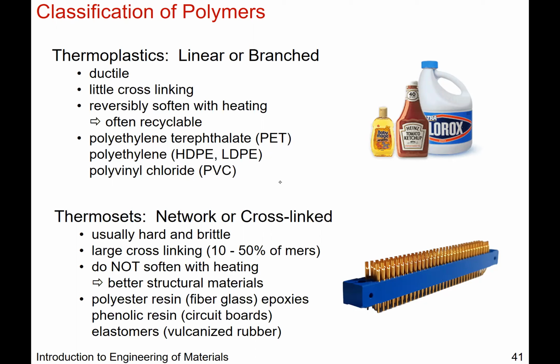This is just a review on some of the terminology that will come across again today. To review, we talked about thermoplastics in the polymer structure module, and these are typically more ductile. There's very little cross-linking. There could be some, but very little. They're linear chains. They could also be branched, but definitely not network, right? And because of this structure, they're typically more amenable to recycling in the sense that we can manipulate the chemistry again to restructure it and reuse the material for another application.